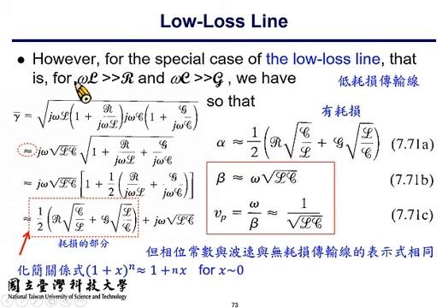So here is the actual description about the propagation constant gamma. However, you can see that the first part and the second part, which are R plus j omega L and G plus j omega C, are modified a little bit. And by assuming that R is small, G is small, so the second term over here is relatively small.